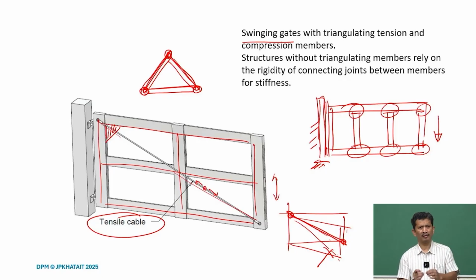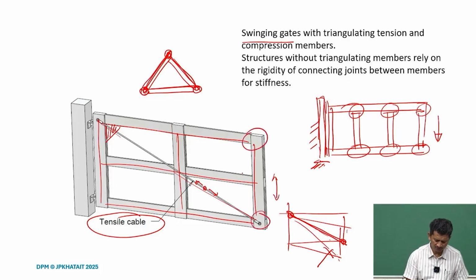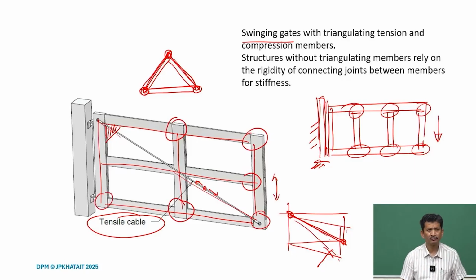So even a cable is good enough, good solutions. And in that case, the moment we have that, we realize that we may not have to worry about these joints anymore. So the same thing applies to any machine frame. If we have that kind of thing in place, we don't have to weld or make those joints very rigid.